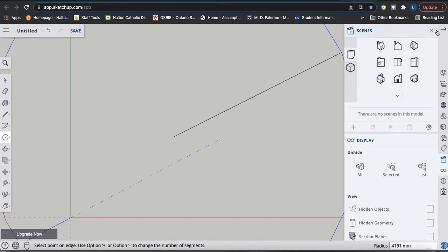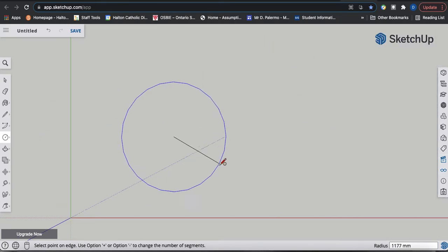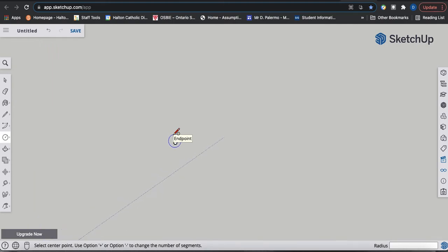Notice that as of now, there's a couple things. In my drawing, I'm giving the diameter, whereas this is looking for the radius, right? So if 22.05 is my diameter, then that means that 11.025 is my radius. So look at the bottom right corner, and you can see how small that is, right? So we're just going to zoom into that spot there and make that look larger for us.